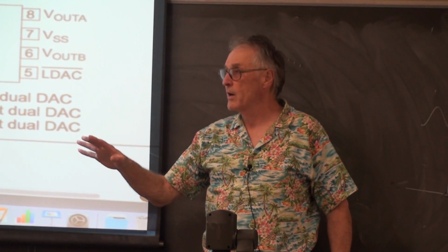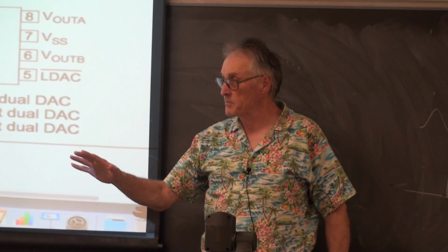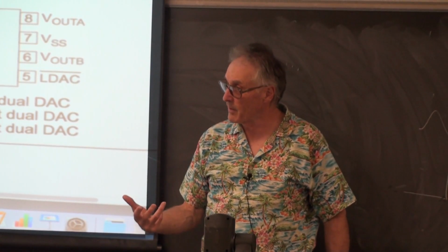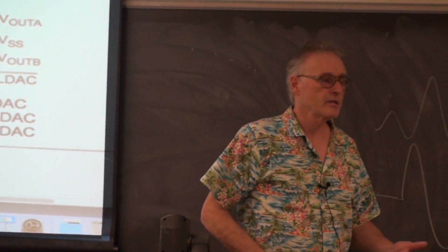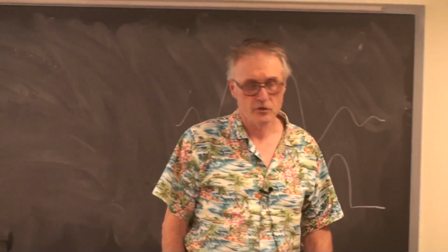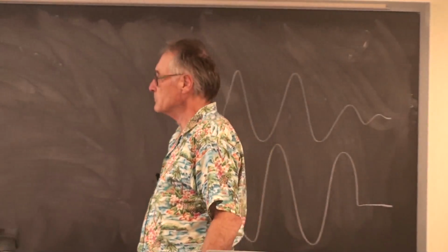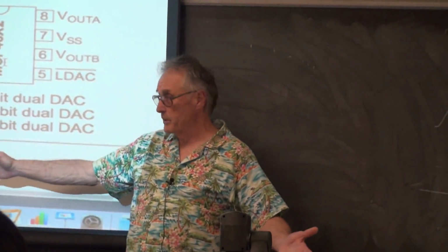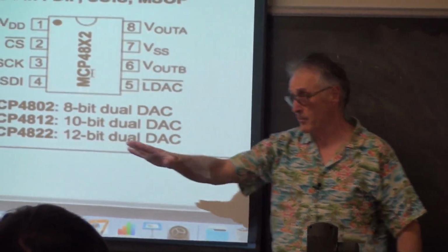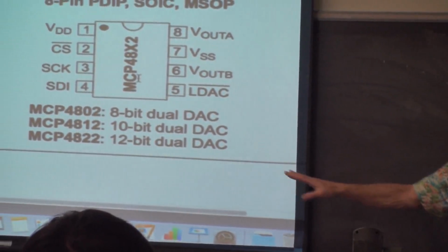And whenever I want to do filtering, I switch to fixed point so I can more easily think about fractions. Fixed point is a scheme for representing fractions in a C integer format. If you don't like thinking in fixed point, don't use it. But I'll talk more about that over the period of this lab.